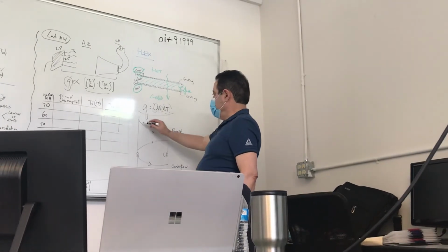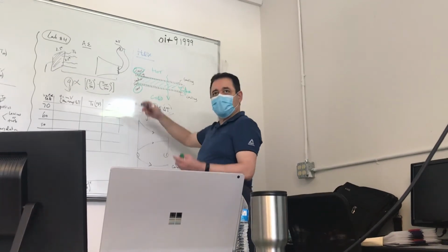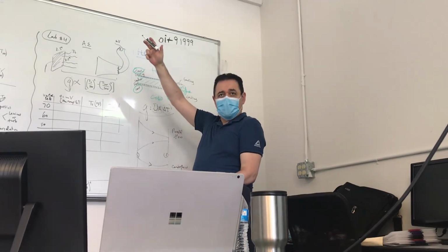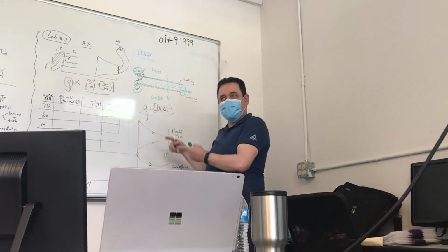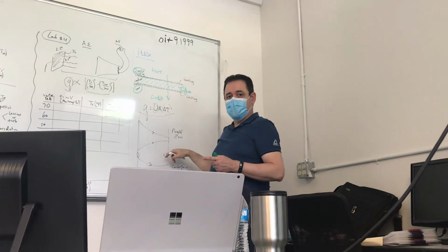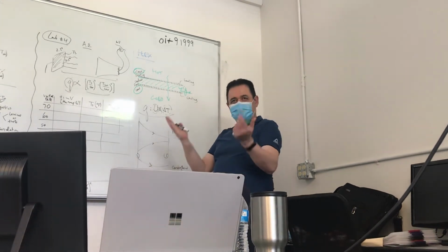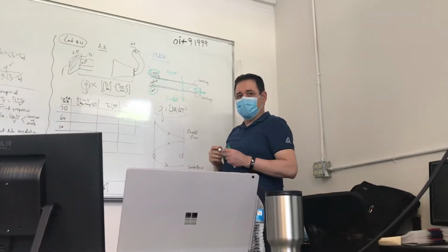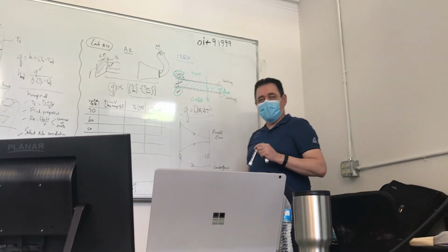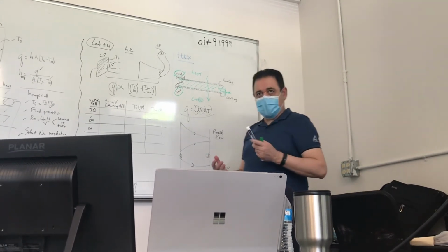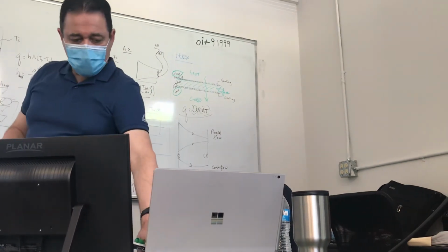Okay? So between the entrance and the exit, you see, for parallel flow, the temperature difference is really high at the entrance, right? And it gets smaller and smaller as you go towards the outside. Whereas for counterflow, it's kind of even throughout the entire thing, right? And remember what we said in MEC 323 is that counterflow is more efficient than parallel flow, given everything is the same.